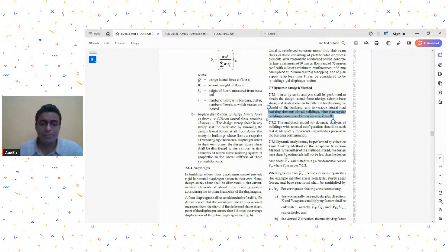So now what I'm trying to explain to you is that for such a short height, and for such a low seismic zone, the behavior you will observe of the structure will be closer to equivalent static anyway. Okay, so it will be mostly a parabolic deformation behavior that you get from an equivalent static approach. So the question of other modes, or the question of modal participation, or the other questions don't appear anyway. Okay,